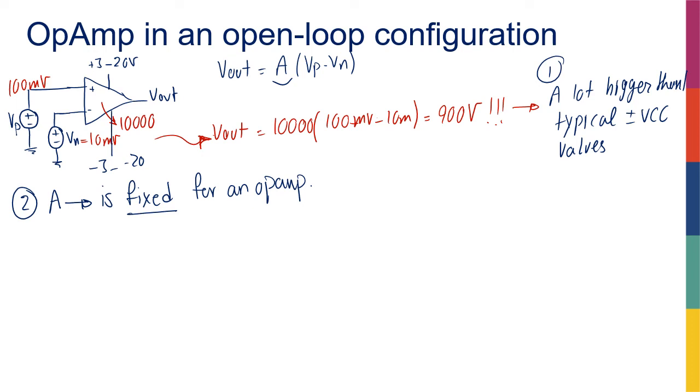You have a little bit of variation after fabrication. It's not that if you design something and fabricate, I don't know, 1,000 or 1,000,000 samples of those ICs, all of them are going to have a gain of 950. Some of them are going to be 1,000, some of them 950, some of them 1,100. It's just a variation. There's an error in that gain, right?